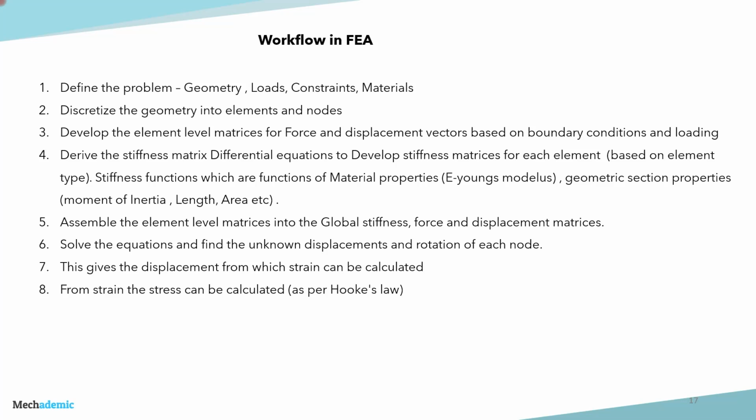First, defining the problem, then discretization, then developing the element level matrices, and then developing the stiffness matrix using the differential equations, and then assembling the element level matrices in the global stiffness matrix, solving to find out the unknown displacements, and from the unknown displacements calculating the stress.